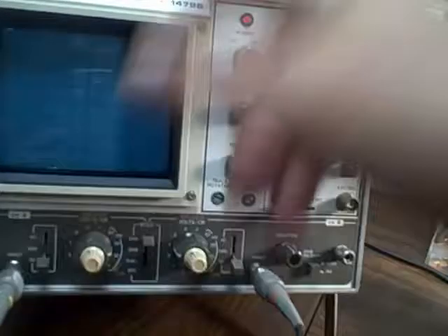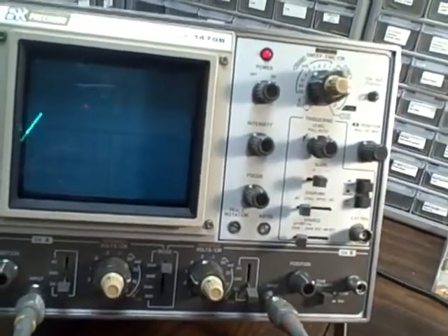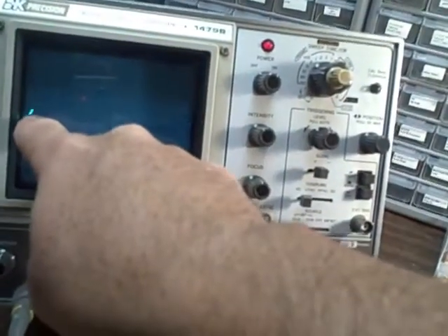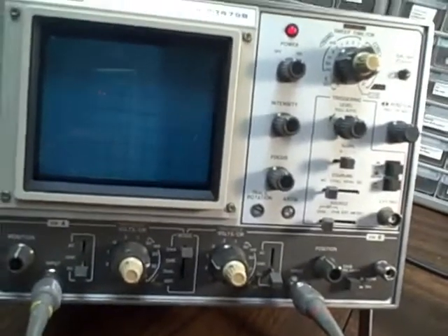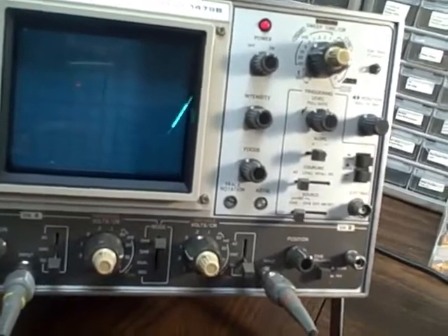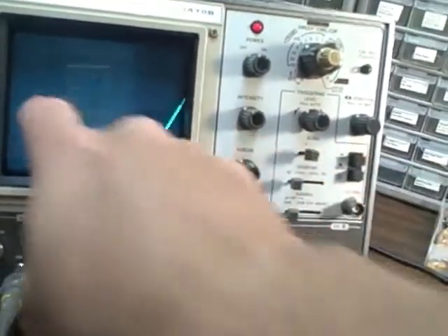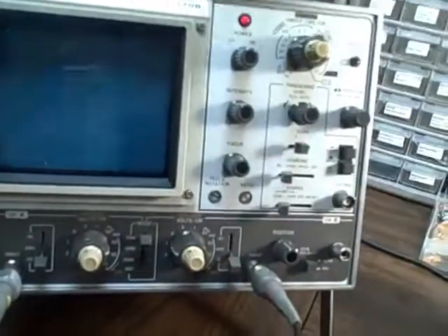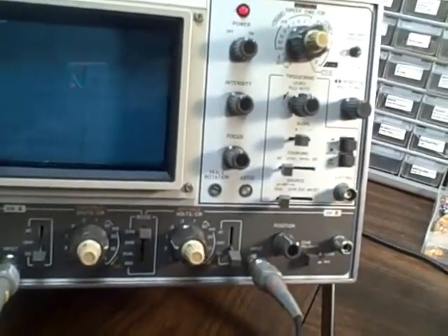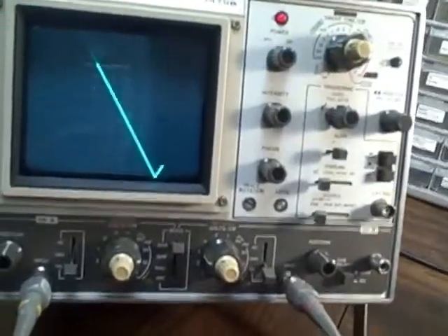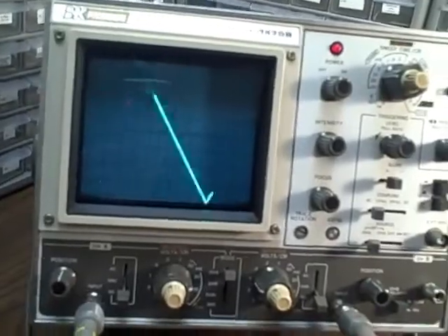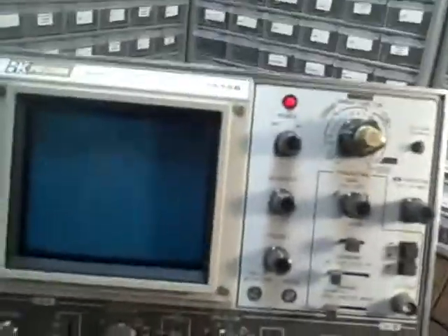So if you see that the line is straight, and you know that this scope was able to measure voltages properly from 0 to maximum and so on, which we did earlier in the vertical test, and we see that we are getting a full cycle within a certain time band, so that our time base is correct, then we also know that our linearity must be correct. Otherwise we'd have a distorted triangle. We don't. We have a linear triangle. So I'm going to use the triangle wave, and we're going to test our time base.